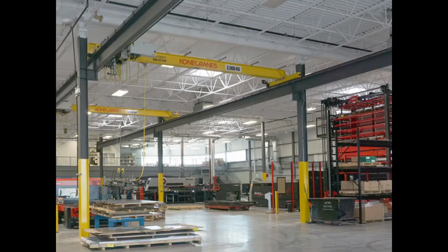Most common, which is something we're not really going to deal with in this course, but in an industrial structure where you're trying to lift and handle material using different kinds of cranes. This is a crane that's supported off some crane supporting columns. This is a column that also has a little standoff here. So in addition to whatever compression this column is going to support from the crane carrying the load, the fact that the reaction is at an offset from the face of the column is also going to introduce some bending. And so that's another example of where we might have strong axis bending paired with compression. And so that's a situation where we would have some combined loading.